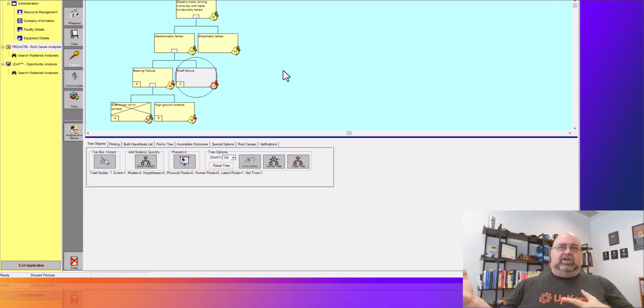One condition I was looking at recently in RCFA had to do with harmonic content, and it was destroying a machine. When we went back, because it was a special order machine, it turned out that somebody along the way neglected to specify that the operating environment included harmonic content. So the OEM just didn't design around it.